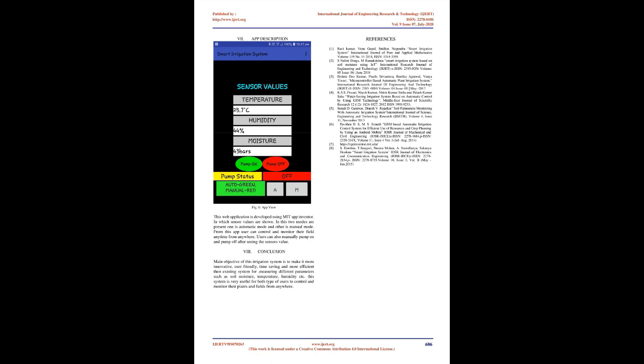6. Circuit Diagram. The circuit diagram is designed using Fritzing software. It is open source software for the design of electronics hardware. The project uses NodeMCU to control a water pump and send information to a web application. It consists of a relay module, water pump, GSM module and sensors. Moisture sensor FC28 measures the level of soil moisture and sends the signal to NodeMCU ESP8266. Then NodeMCU will open the water pump if moisture is below the threshold value.